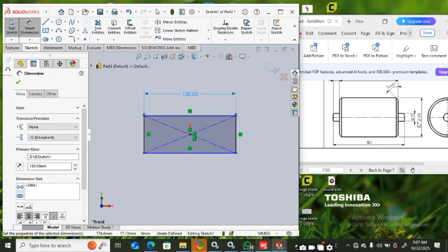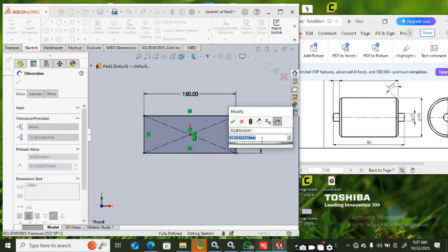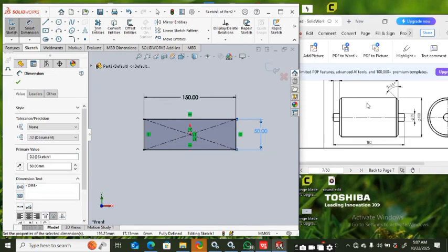So we're going to design it, but before we do that, mind you, we are drawing this in halfway, so it's not ideal you make it 100, because if you divide this by halfway, it's going to be 50, right? So I'm going to make sure that this particular line is 50. So we're going to make it 50, and then that's it. Before we continue, we're going to chamfer this model. We're going to make sure that this thing has a chamfer.